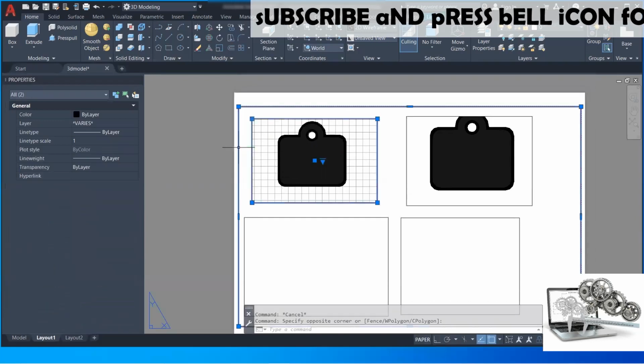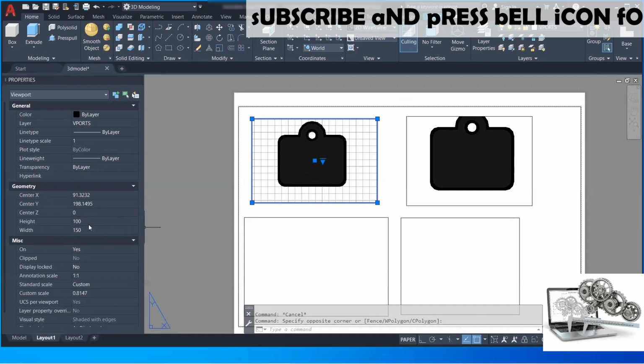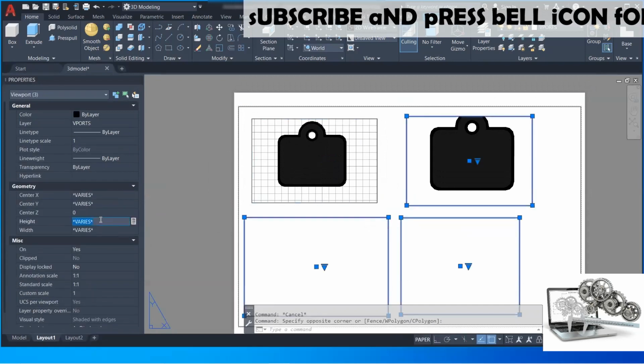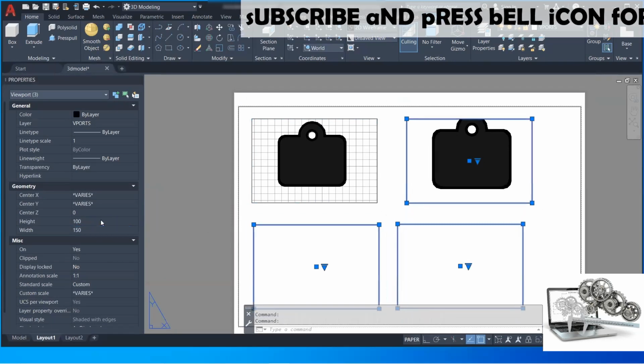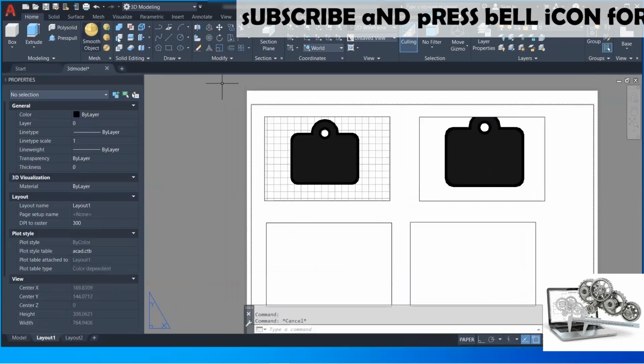So we have maintained this as 100. Now select the other three viewports and change their height and width also, 100 and 150. Press enter. Okay, now press escape key.